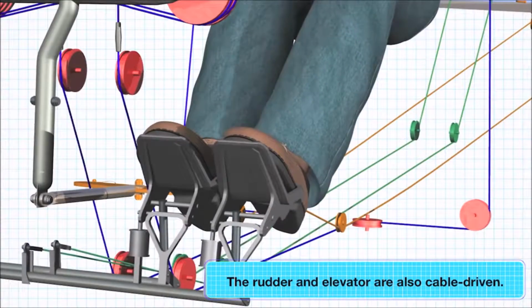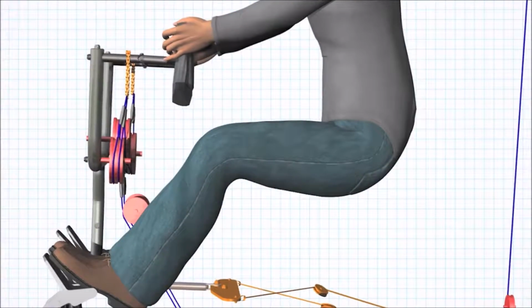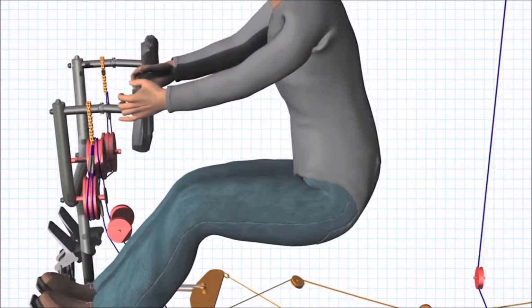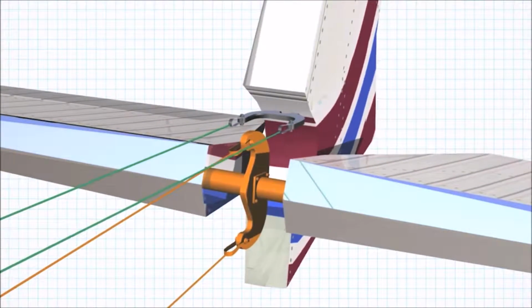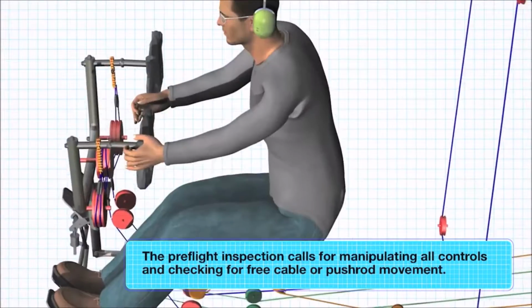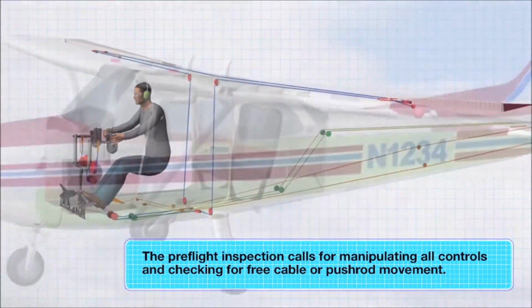One of the advantages of the mechanical flight control system is that you can feel the wind pushing against the control surfaces. This is good for pilot training. The pre-flight inspection calls for manipulating all controls and checking for free cable or pushrod movement.